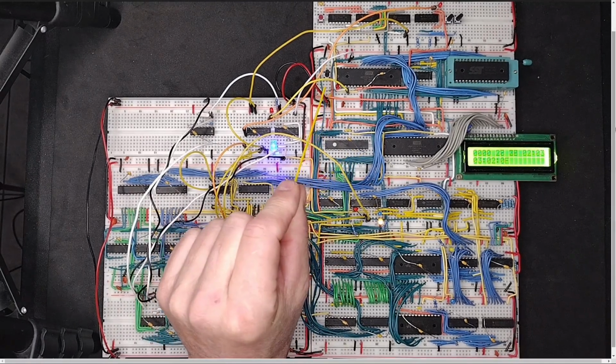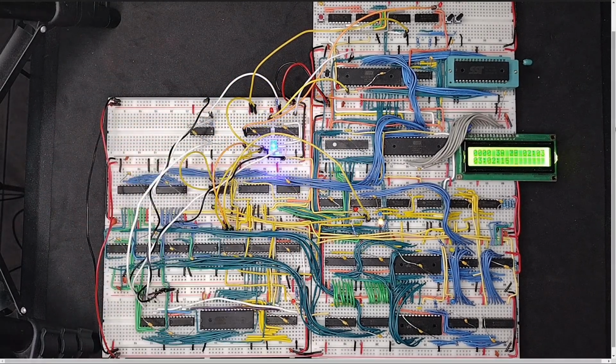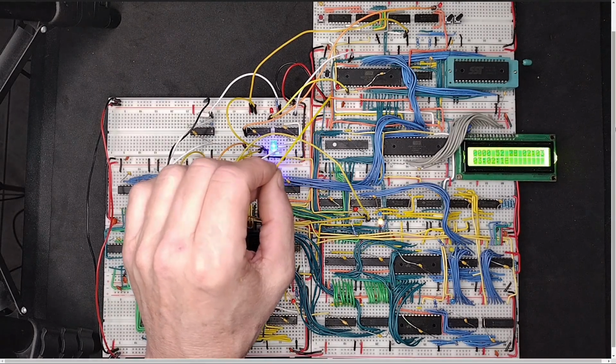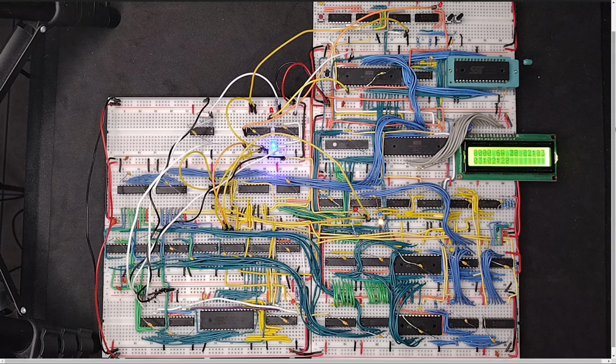And we also need it so that when we're in a wait condition, if you recall, when you call the 65C02 wait instruction, then the halt line, or the ready line, will go low, and the computer will wait until there is a negative on the interrupt. It doesn't matter how long that interrupt is. It could be a very short pulse of a negative on pin 4, the IRQ pin, and then it will begin processing again.